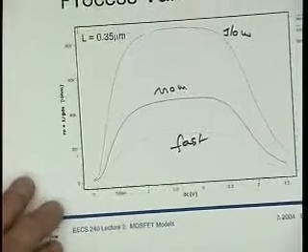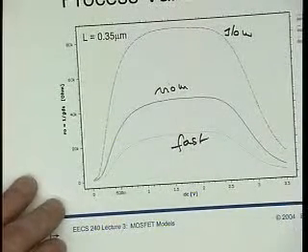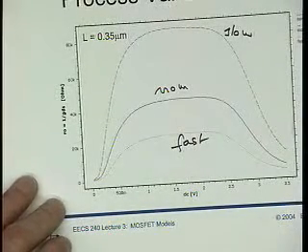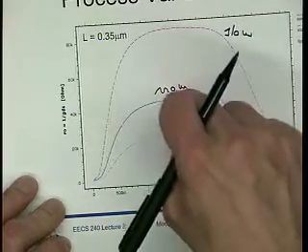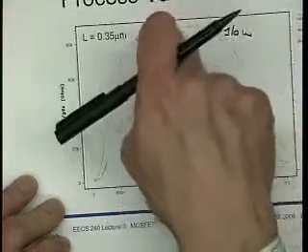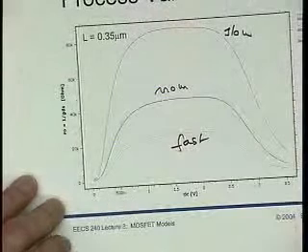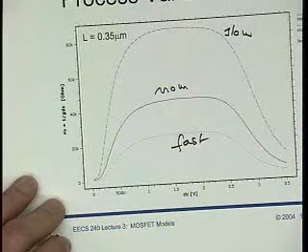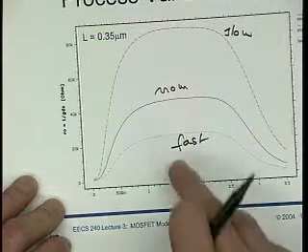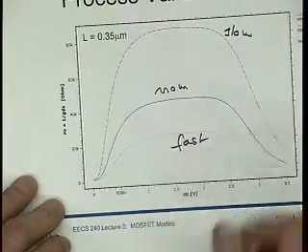So it's also not exactly something to rely on, right? We better not build circuits that work for R-out 40 kilohm but wouldn't work for R-out 80 kilohm, and wouldn't work for R-out 20. Rather, what we will design is circuits that work for any R-out that's larger than 20.